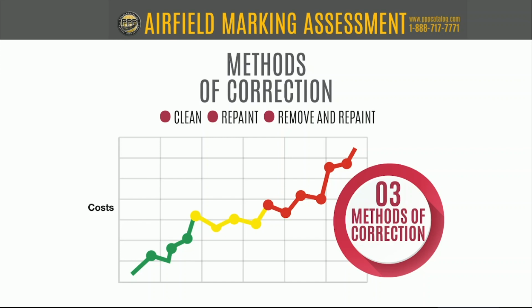And to understand, kind of as Mike said, many times I've seen this knee-jerk reaction is, let's just paint over the top of the defect. And that rarely ends well, especially if you have a peeling problem, or if you have, for instance, mold, mildew, that kind of thing, because a lot of times that paint will stick to the mold and the mildew. As I said earlier, it'll stick to whatever it's sticking to. But if that's not sticking to what's under it, you're going to have problems, and you're going to have some peeling and so forth as well.